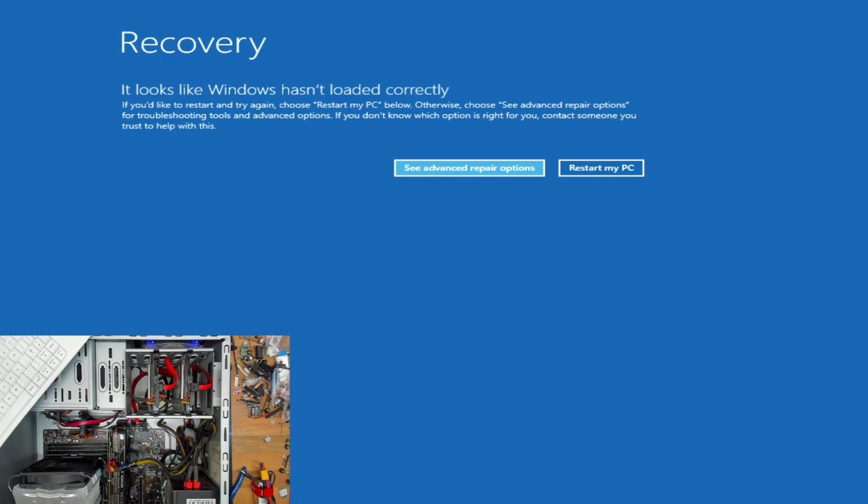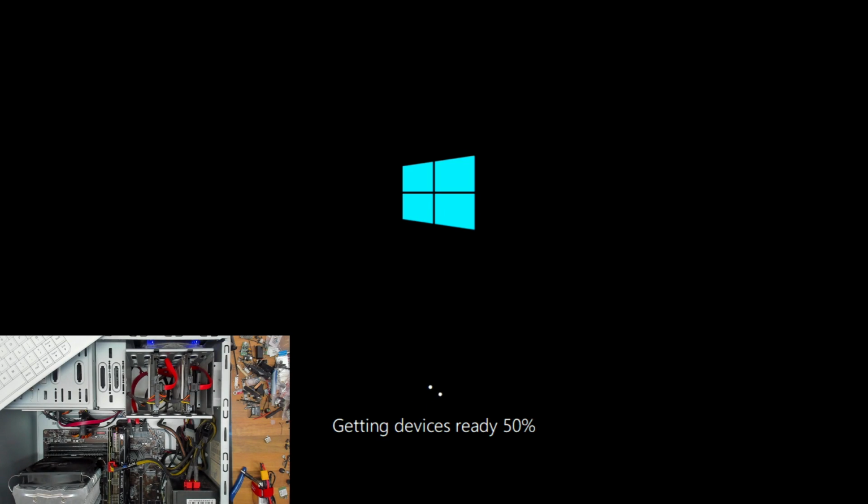Oh, well, that's good enough for me. Okay, so since trying to connect the drives up to a similar period motherboard was a bust, I just plugged them back in, went into the BIOS and set the BIOS on the new motherboard into RAID mode, and it actually just detected the two member disks and just started working. I have to admit, I haven't used RAID much.